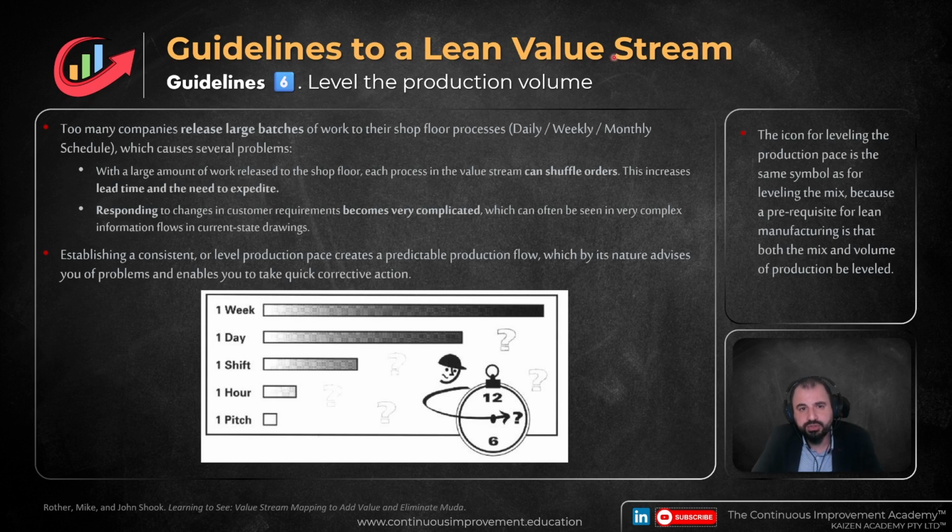So instead of this, you establish a consistent level production pace through what's called the paced withdrawal. And this means regularly releasing small, consistent increments of production instructions at the pacemaker process. So you don't schedule the pacemaker process for a complete week, or even a day, but you try to reduce that scheduling interval so that you are very responsive and you avoid the problem of producing much more than what your customer would require.